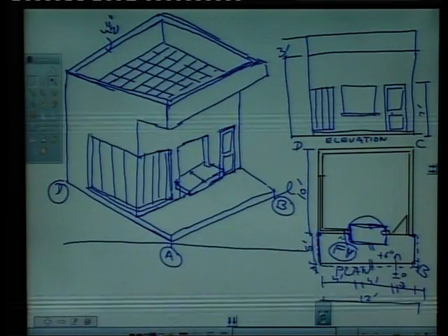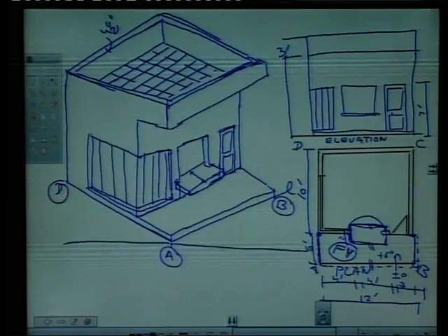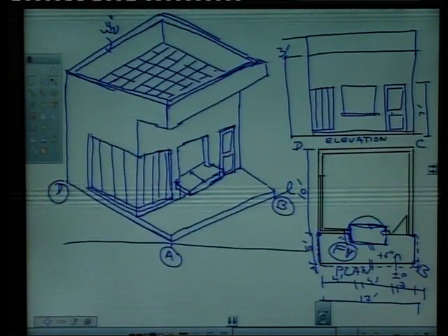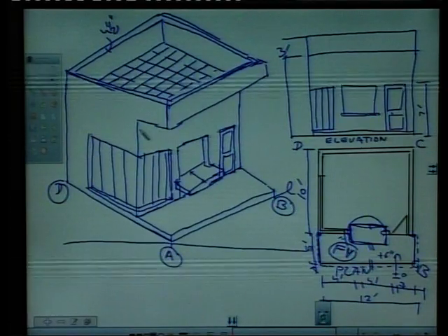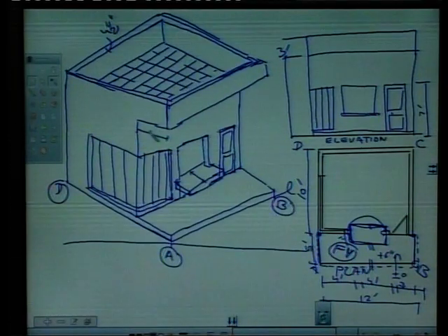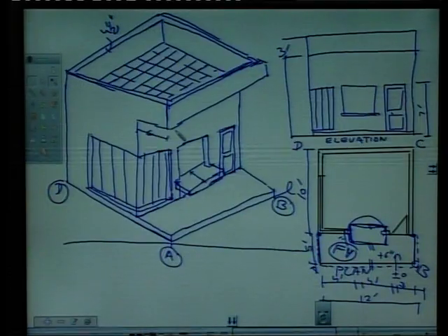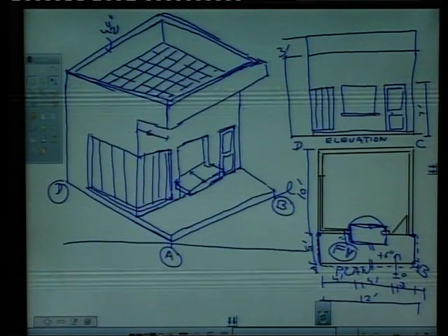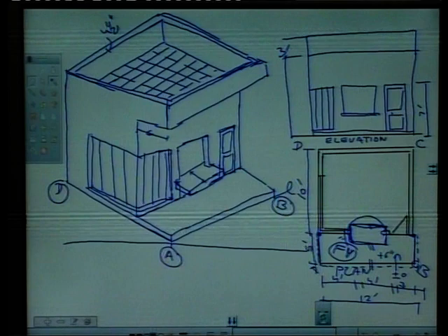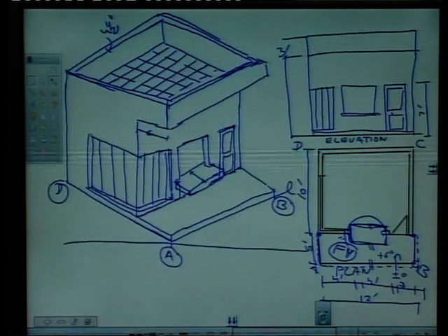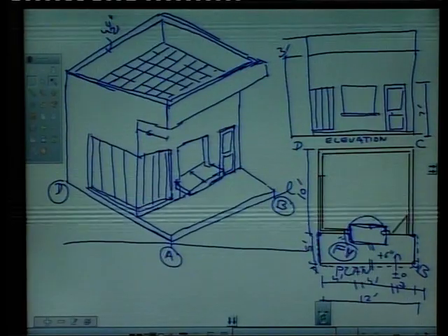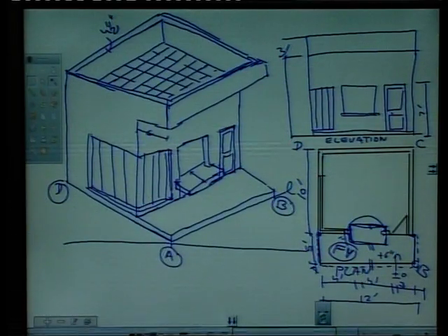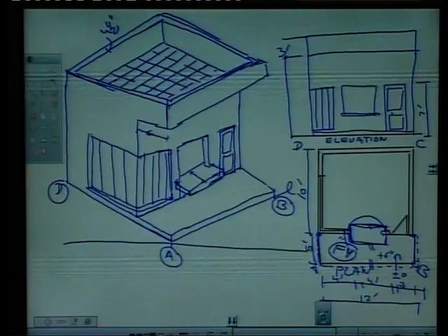I hope it is clear. We have drawn everything. This is the L-shaped window, counter, door, parapet. This parapet is extending 5 feet. So, this is basically 5 feet here. This overhang is 5 feet. This completes our isometric drawing of the security post. You practice it on the drawing board with proper instruments, so that will clear your concepts. Now, let us take one more example.